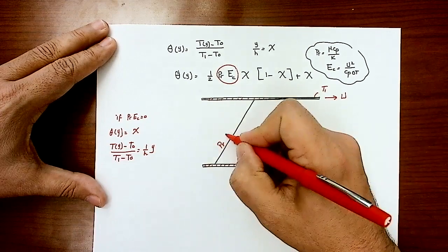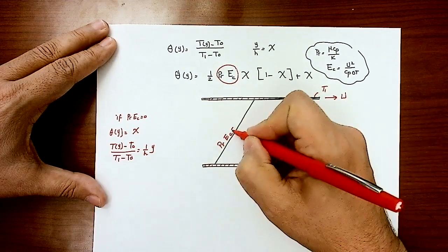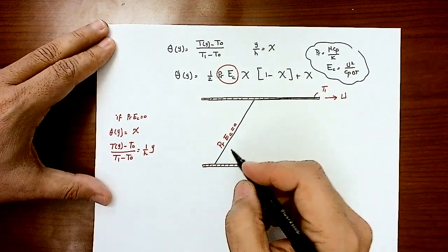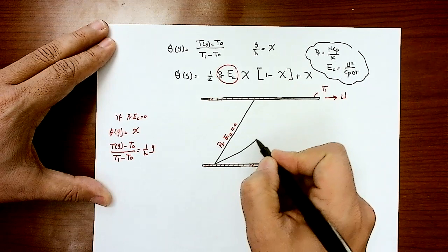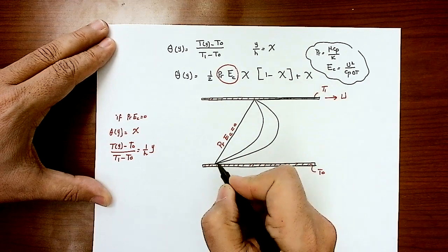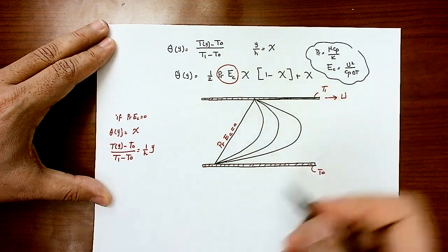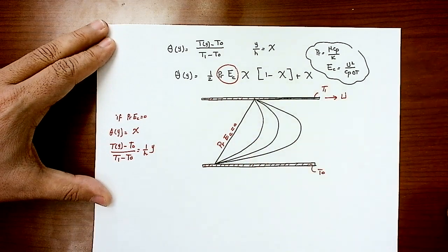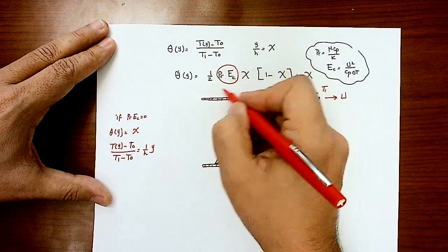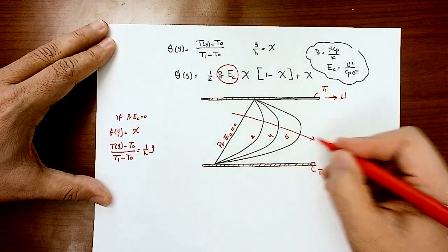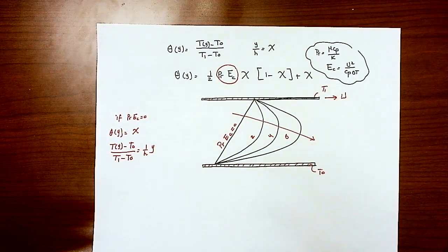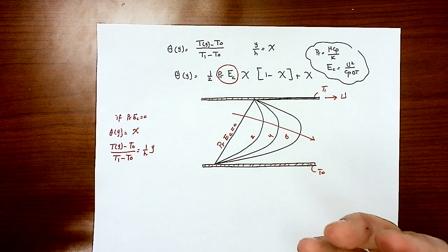This is for the combination of Prandtl times Eckert equal to 0. If you change that value, you will start getting a parabolic profile. For example, if that value is equal to 2, 4, 6, the more you increase that term, the Eckert number effect increases, right?